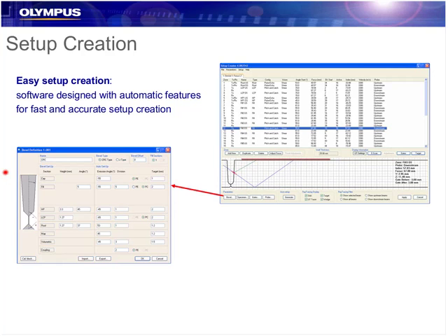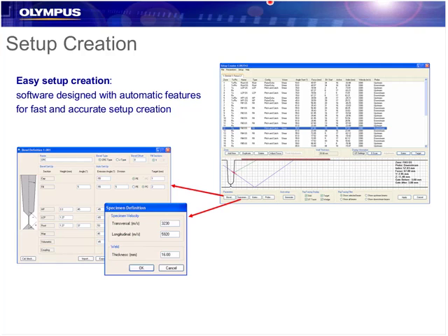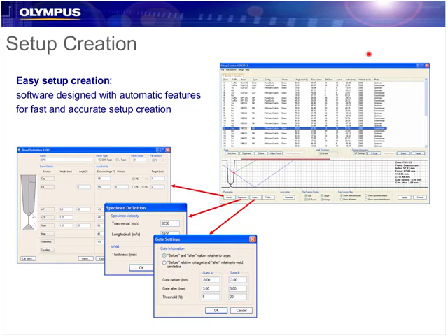So here we'll be able to very precisely put in finite measurements for all of the joint design and geometry. And from there, things like velocity, thicknesses, all the part geometry, and also gate settings. So you'll see in the slides coming up how important the gates are. The gates basically define our zones, and we're able to define those very well and they help us position flaws very accurately.